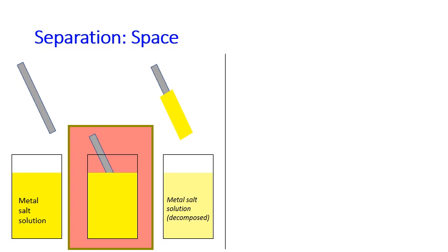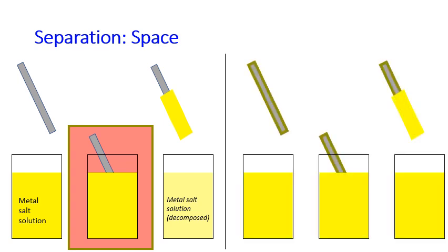What can we improve from this example? Well, if you think about the conflict, the process needs to be hot, and it is useful to coat the metal, but it is harmful to the solution. So to separate the zone of the conflict in terms of space, now we heat the metal first. So before you put the metal into the solution, you heat the metal.